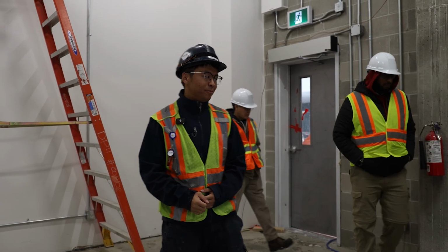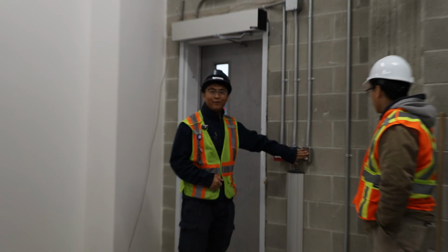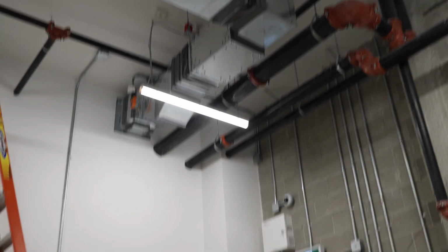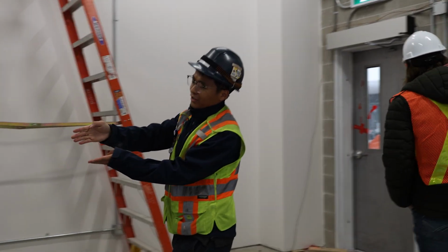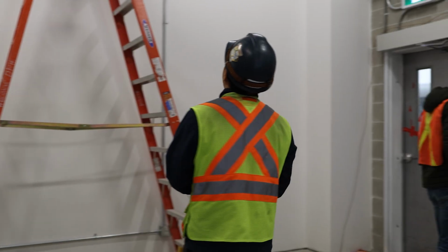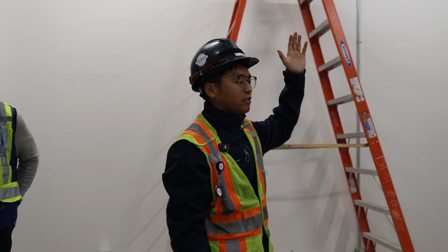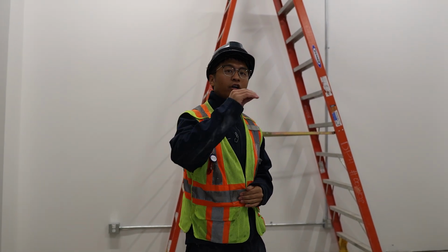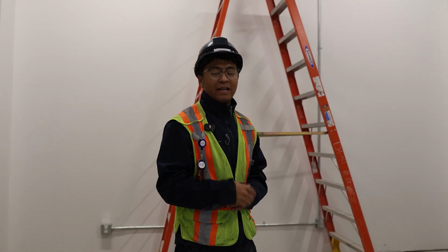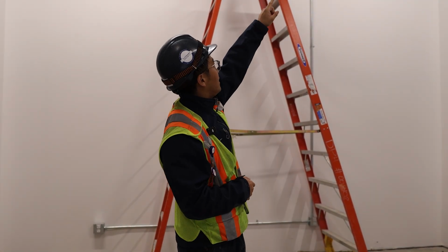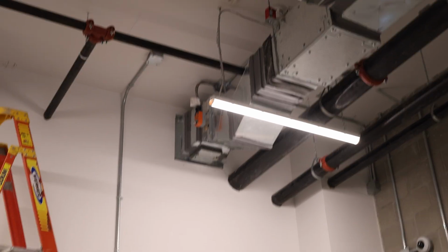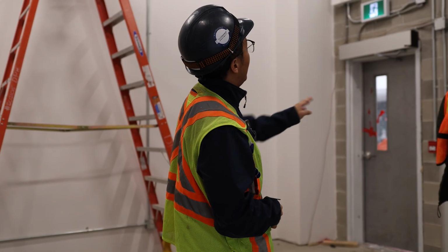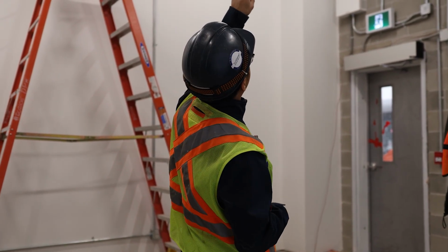Hello everyone, welcome to the garbage room. The BMS is monitoring the space temperature for the room, and we also control the exhaust fan and the damper. We also monitor the sump pit in the garbage room. And the sequence for the exhaust fan is the exhaust fan stays running the whole time, unless the outside temperature drops below 5 degrees set point, and that set point is adjustable. And that's the actuator for the exhaust fan. The actuator has to be verified open before we turn on the fan. For this room, we only monitor the space temperature and no space pressure, and turn on the exhaust fan.